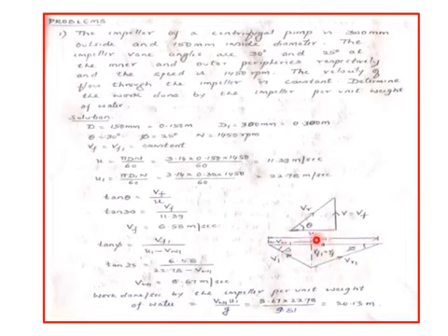Now, using the outlet velocity triangle, we know that the jet leaves in the tangential direction, that is VR1. By the time the vane would have moved with velocity U1. Therefore the jet leaves at an angle beta, which is V1. The component of V1 in the radial direction is Vf1. The component in the direction of motion of the vane is Vw1. Therefore this component is U1 minus Vw1. Now you can write tan phi equals Vf1 by U1 minus Vw1. From there we can get Vw1.